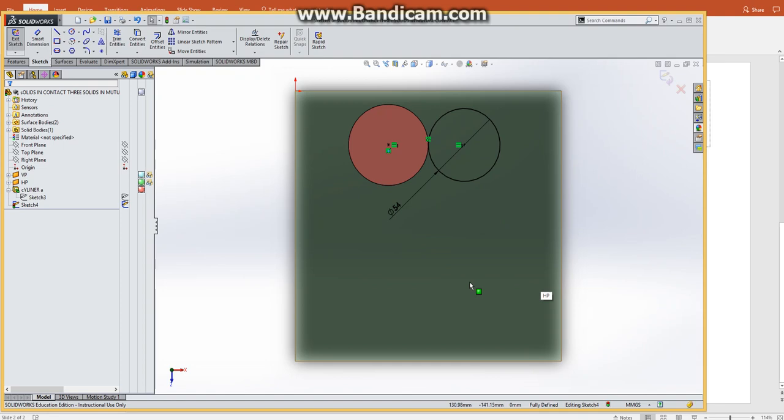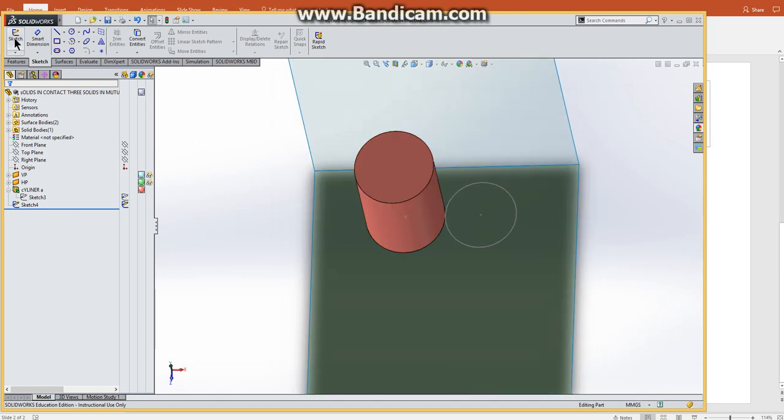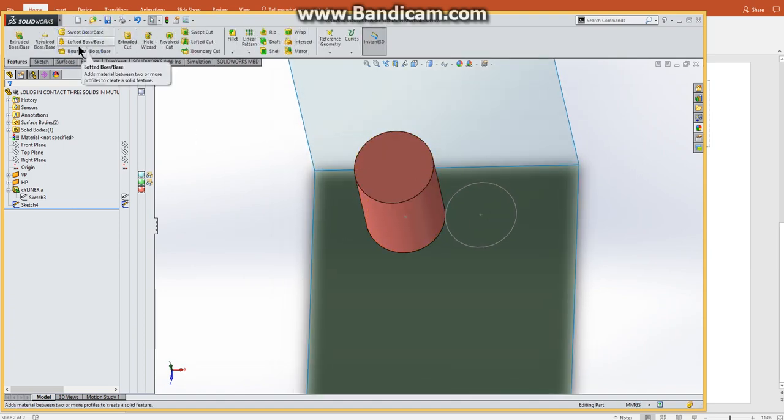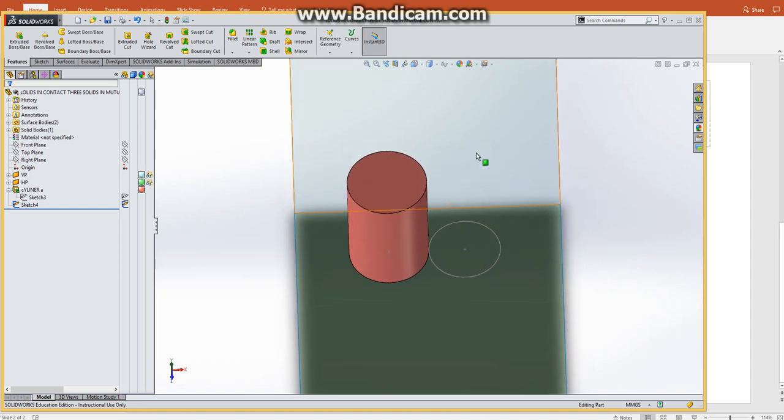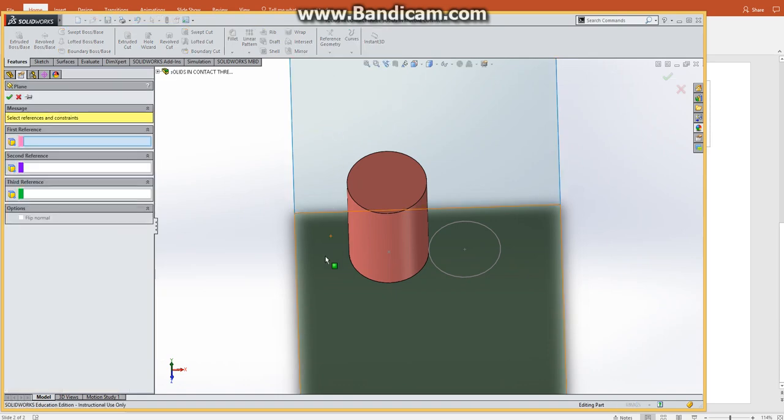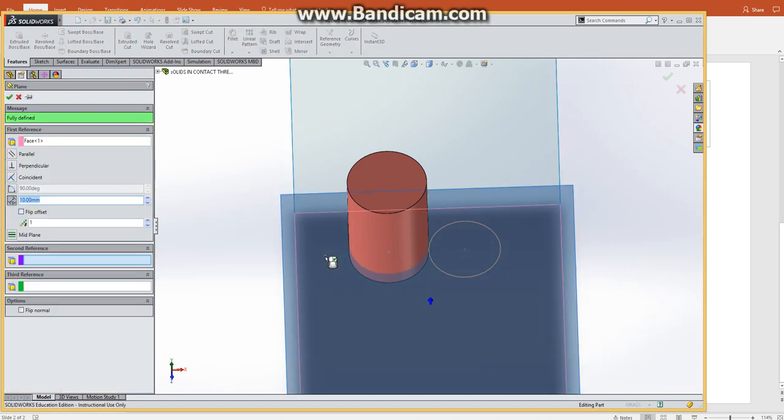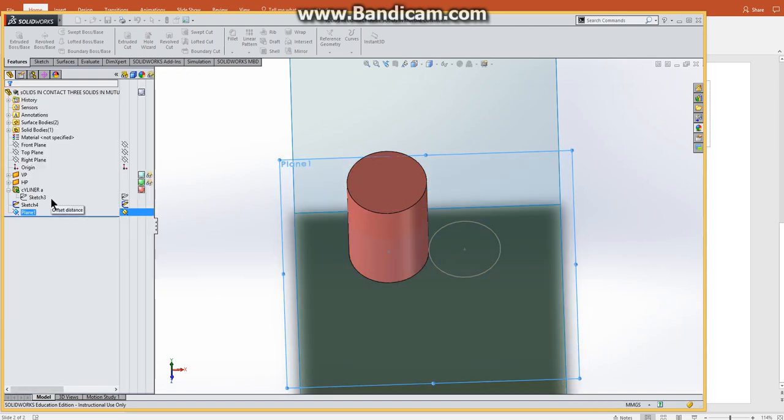Now we're going to make a cone using a loft. So I'm going to exit sketch here. A loft is this button here. I need two sketches. So I need to sketch the apex of the cone, the top of the cone, up higher here. So I'm going to go Reference Geometry, Plane, select this horizontal plane here, and have a distance of 50 from it because the cone has an altitude of 50.